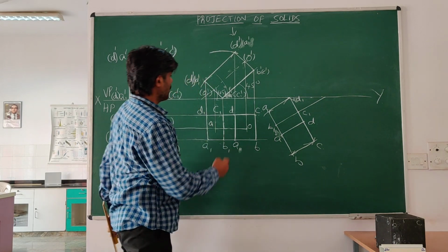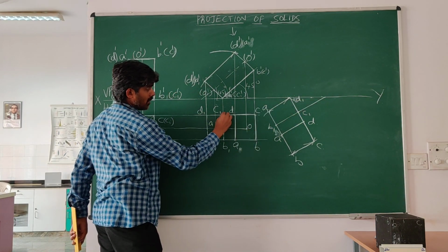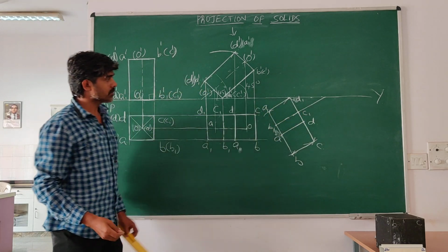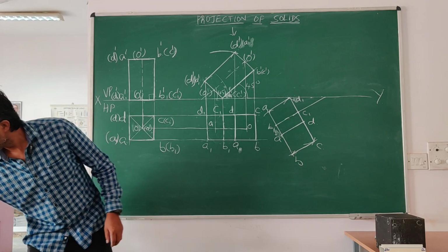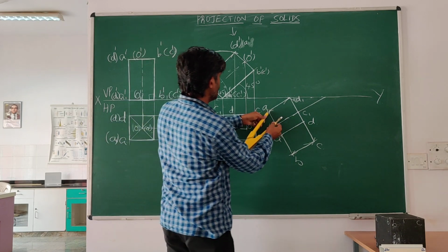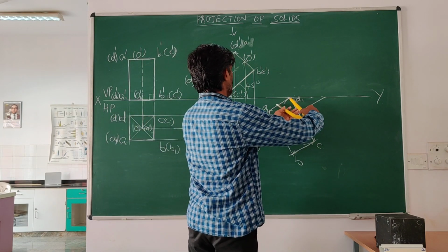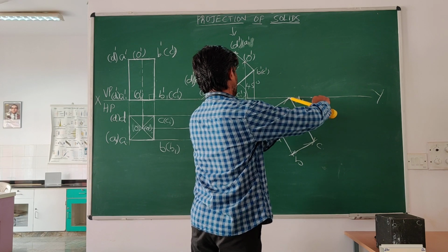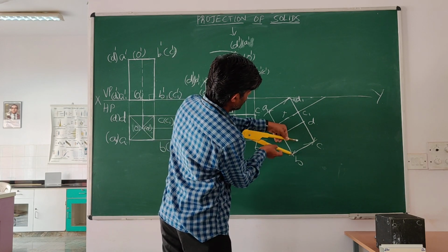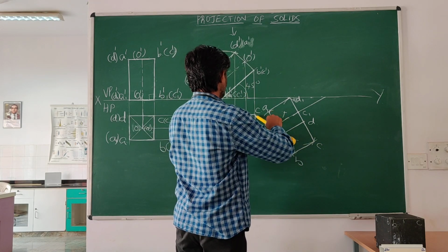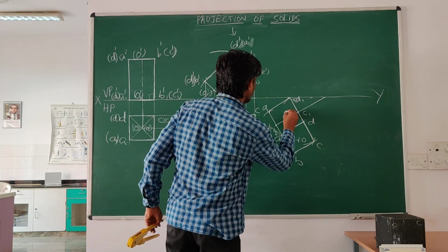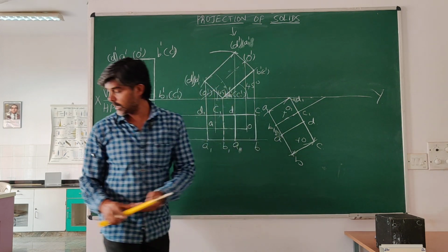Now, this is the reference line already drawn. However, this is a hidden line, so I should make this line also hidden. Now, if you want, you can just take these two points, these two are equal, to locate. Similarly here, B2O and C2O. So this point is O, O1.